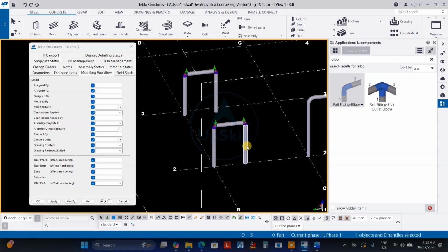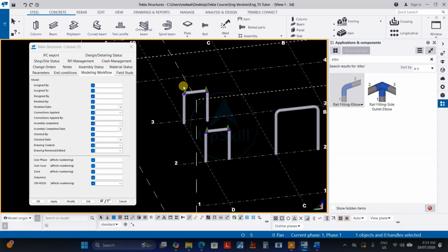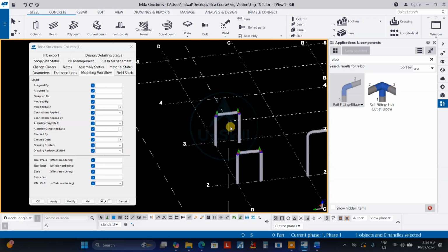Both have the same number, and only one place in the erection drawing is found, only one place of that particular phase, because this phase is not started at the time and the other one has already started. So one member will remain and will not be erected at that time. It may be erected after 3 or 4 months. So this issue will come out if we do not give the number affecting.